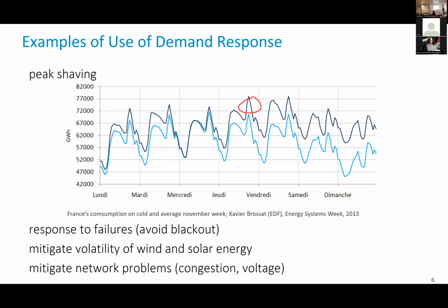What happens when we interrupt the supply is called a cascading effect. If I interrupt the supply, for example, we break a line between France and Switzerland, and we're at a point of time where there was a power transfer from France through Switzerland to Italy. Then Italy does not receive all the power it was supposed to receive. Then what will happen is that, because we've seen that the flows of power are dictated by the complex voltages and not by routing tables, the flows will change everywhere on the grid.